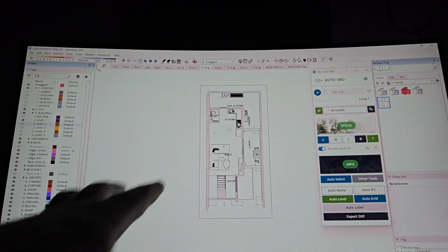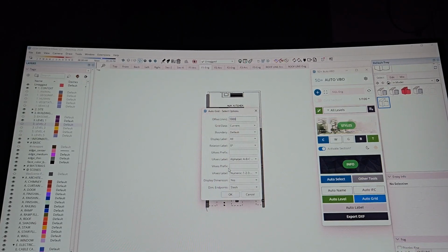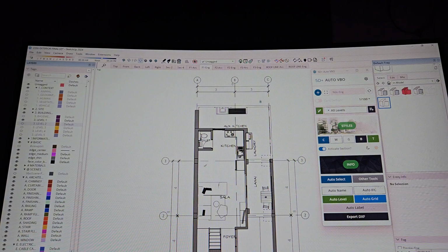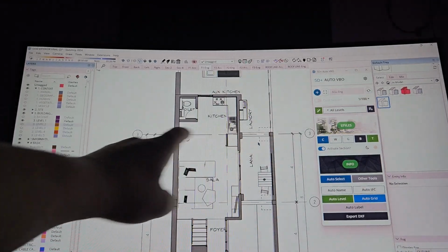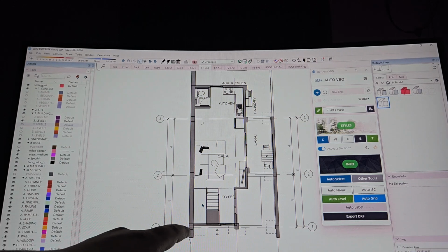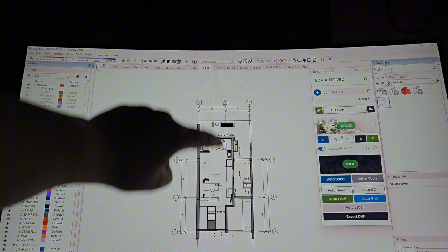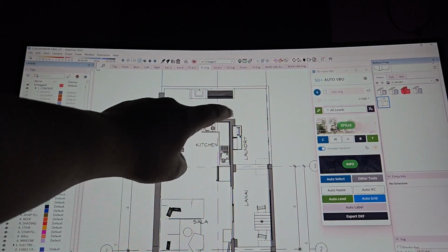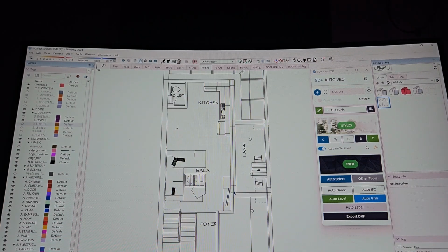However, the nice thing here, this one works by detecting names. So for example, auto grid, okay? You know your index keys. That's the grid, alright? It works by detecting the word column and then putting it at the center. So if it does not detect the word column, then it will be hard. This letter B detected this column, and letter C detected this column. Now I need this column to be detected as well. So let's try to go inside and fix that.